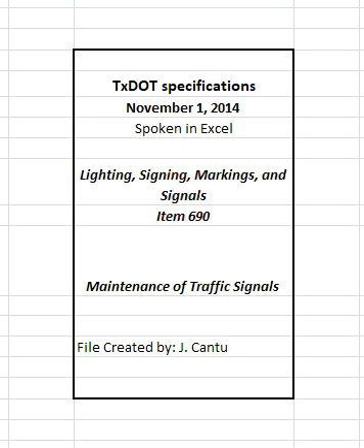Mount signal heads by a span wire hanger clamp, bracket arm assembly, or mast arm bracket assembly. Signal head assemblies consist of 1 to 12 signal sections. Install signal heads as shown on the plans, or as directed. Assemble the signal heads with back plates, louvers, and brackets as needed. Mount all signal heads at the same elevation. Install signal head perpendicular to the travel lane it controls. Plumb all signal heads vertically and horizontally.